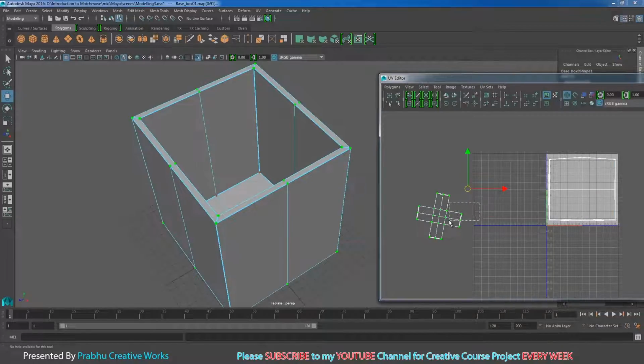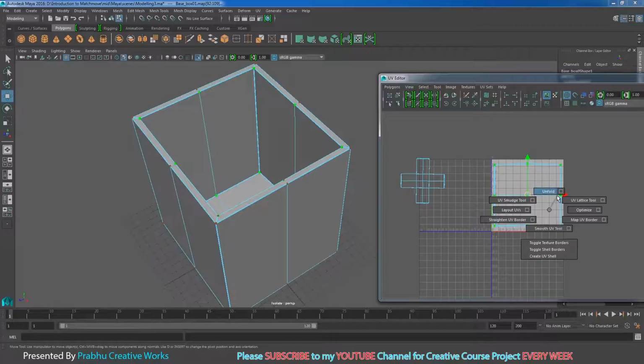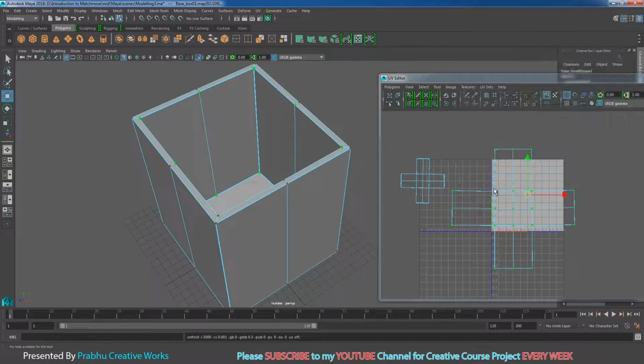Now right click and choose UV, Control right click and choose UV shell, and press E and rotate it straight, then press W and move it near this one. Now you select this whole UV. In UV mode you select the whole thing. Control right click and choose UV shell, shift right click and choose the unfold option box, choose legacy and choose apply and close.